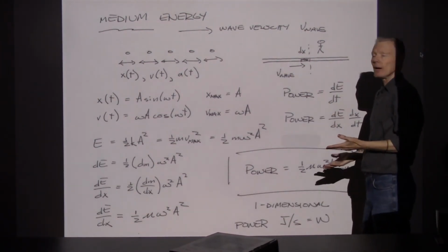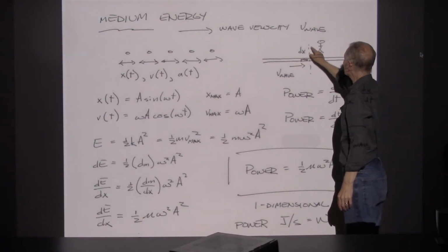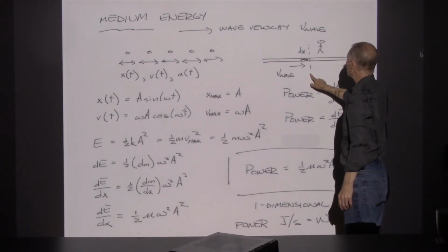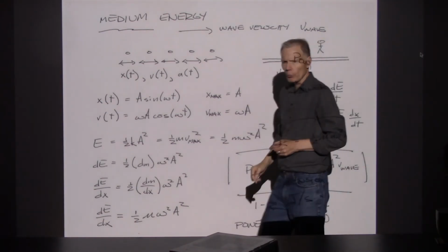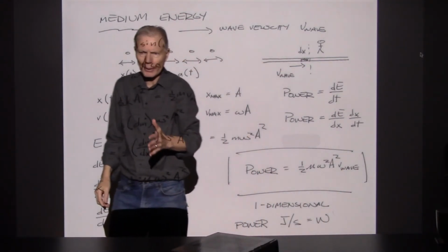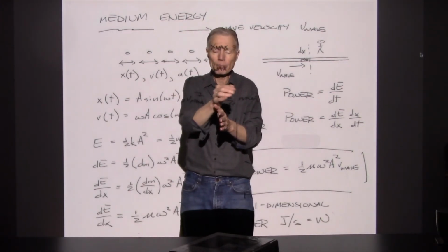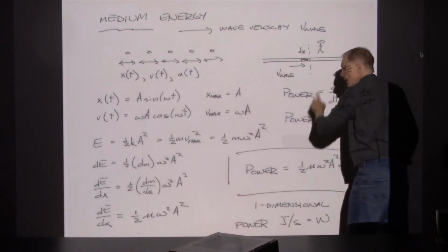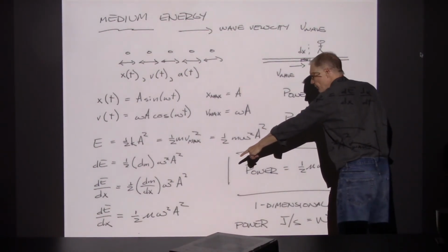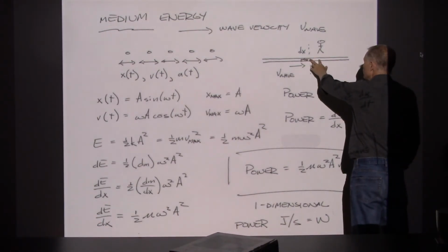The question then becomes, at what rate is the energy stored here crossing this boundary that I set up? See, we're standing right there, watching the energy go by, and we've drawn a line on the wire, and said that we are going to count all the energy as it goes by. Right now there's a little bit of energy stored in that region of dx, and it's that much energy right there. At what rate is the dx energy going to cross over to the other side?